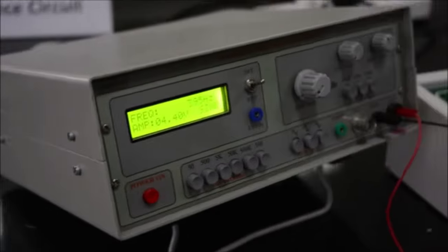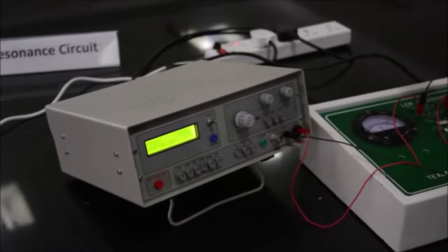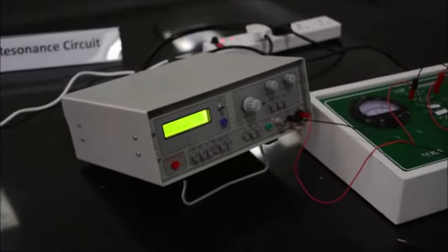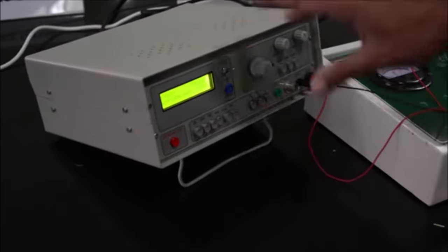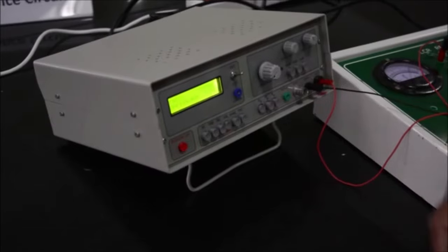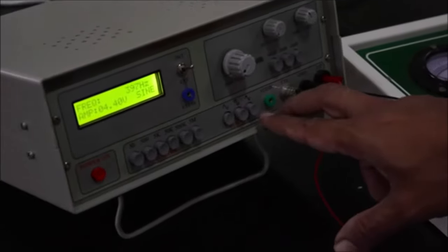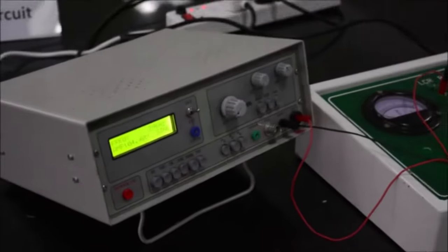Now before we start the experiment, you should calculate the theoretical value of the resonant frequency, so that you vary around that range. The range of variation should include the resonant frequency. So I have now set it at 50K. Hopefully that will include the resonant frequency. And you notice that the knob for sine wave is pressed. This instrument can also produce a triangular wave and a square wave, but we will go for sine wave. Now everything is set.